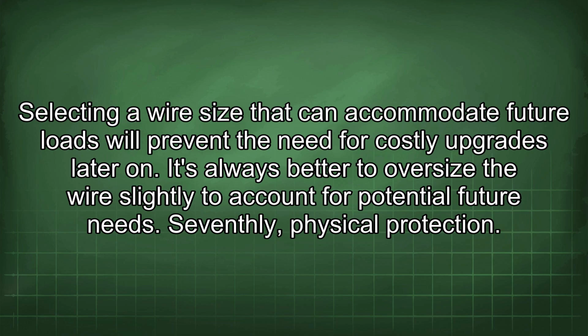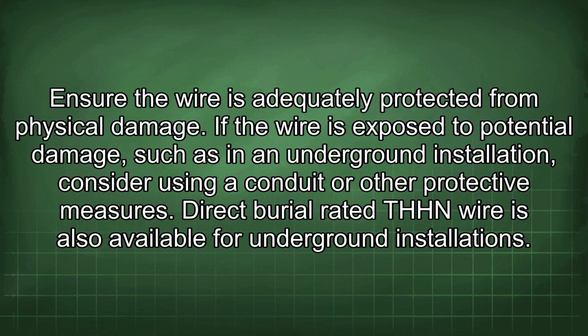Seventhly, physical protection. Ensure the wire is adequately protected from physical damage. If the wire is exposed to potential damage, such as in an underground installation, consider using a conduit or other protective measures. Direct burial rated THHN wire is also available for underground installations.